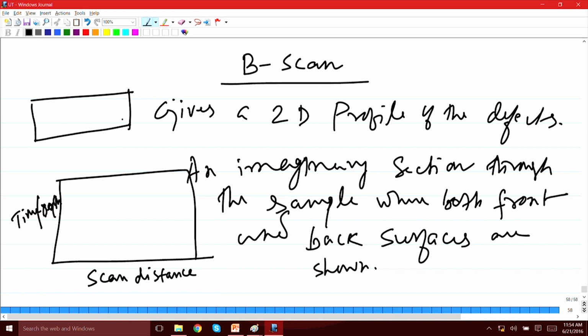and you have 2 defects at 2 different depths, and now you have taken this probe and you are moving the probe on the surface. So, the moment it goes over these defects, then you will see them coming in this display at that particular depth like this.